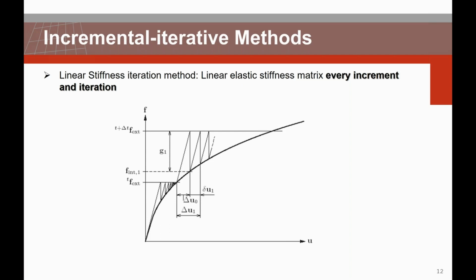the first phase. If the constant stiffness iteration is used since the first increment, this method is basically the same as the linear stiffness method. The constant stiffness method can be used if Newton-Raphson or quasi-Newton method fails after a certain number of increments.